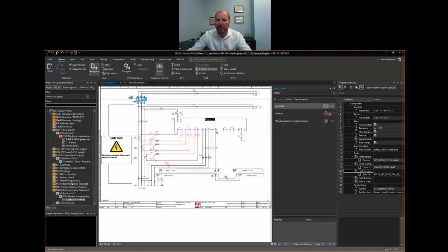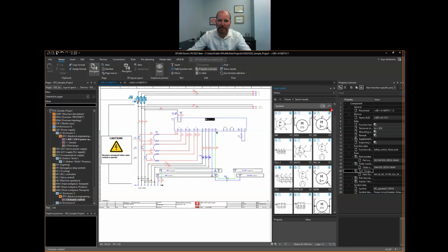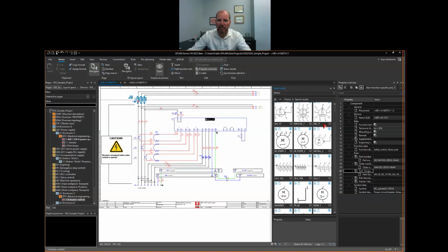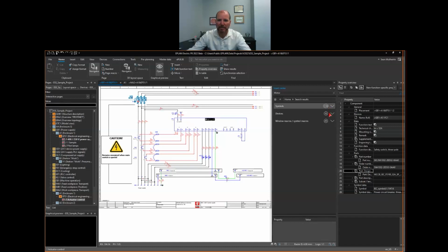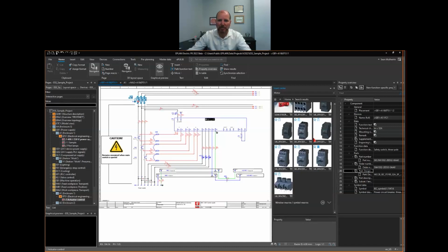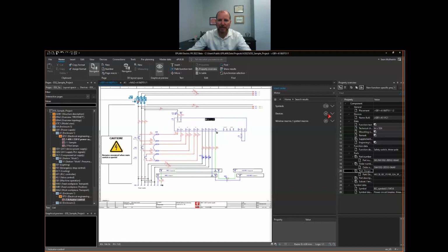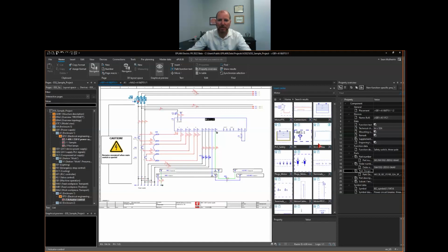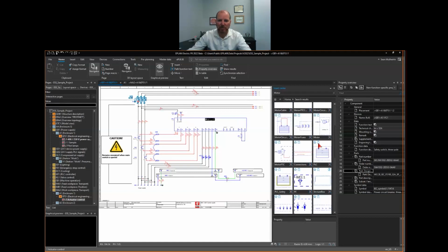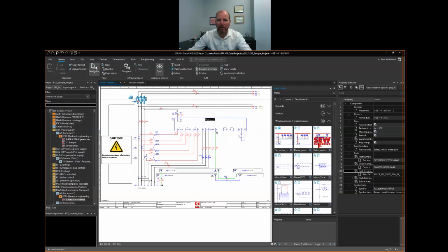And here we've got 118 symbols that have that text either in the name or in the description. We've got 13 devices and 35 macros. So here, by opening the different categories, I can see all of the symbols that were relevant to that particular text, my devices in my parts management that have that text, or my macros that have been labeled with a description or a name according to motor.